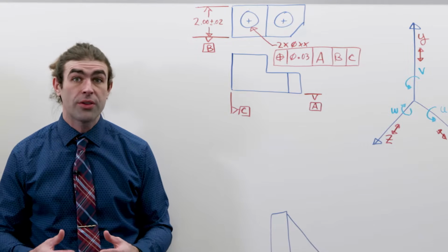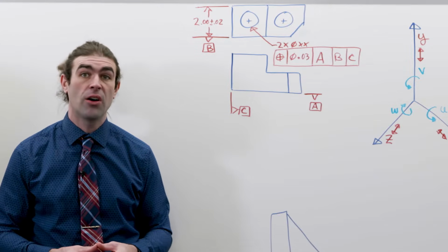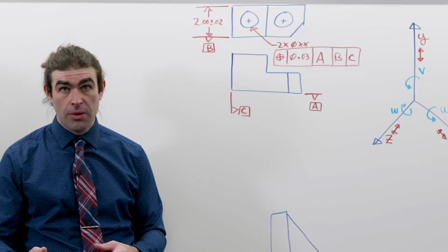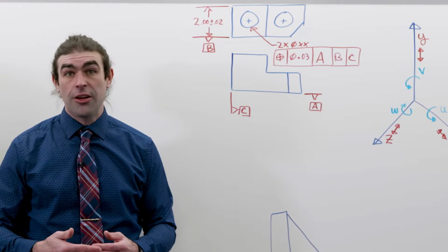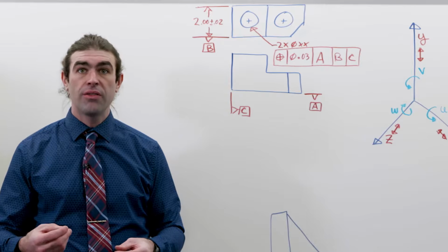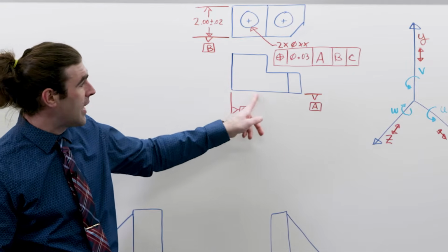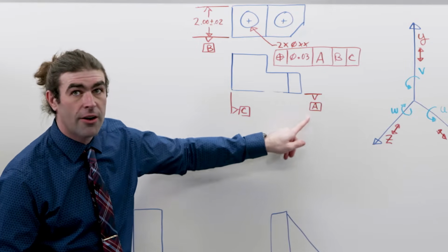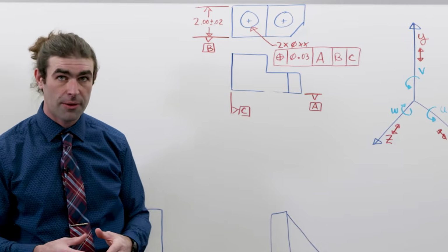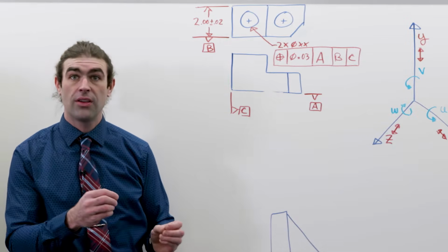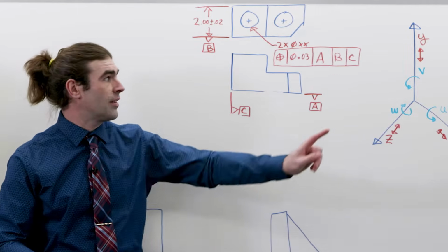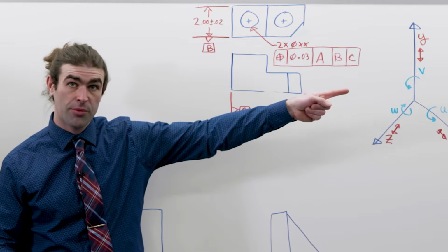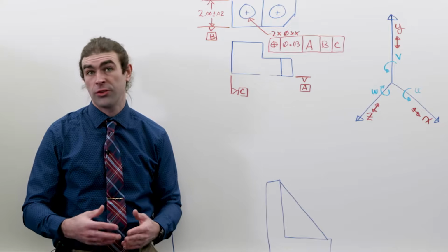Now I want to talk about some of the ways datums are identified on the drawing. If I didn't go through it before, the terminology with this: a datum is a perfect line, point, or plane. A datum feature is a physical portion of the part. So this plane is our datum feature. Datum feature symbol is this little guy. So the letter in a box with a little triangle pointed to something. It tells you which feature is a datum. The datum reference is in the feature control frame, tells you what order to use your datums and at what material condition the datums apply. And then the datum feature simulator is just your inspection equipment.